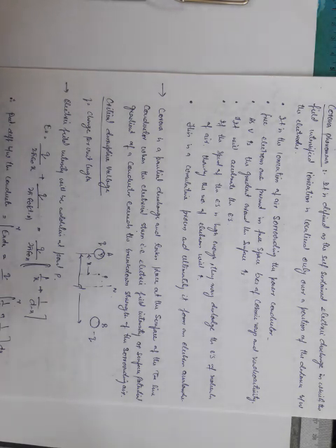So we can say it is a potential discharge, and it takes place at the surface of the conductor or around the surface of the conductor. When the voltage of the conductor goes beyond the breakdown strength of the air, it results in the breakdown of the air, and that part of air becomes conducting, or we can say there are a lot of electrons available.